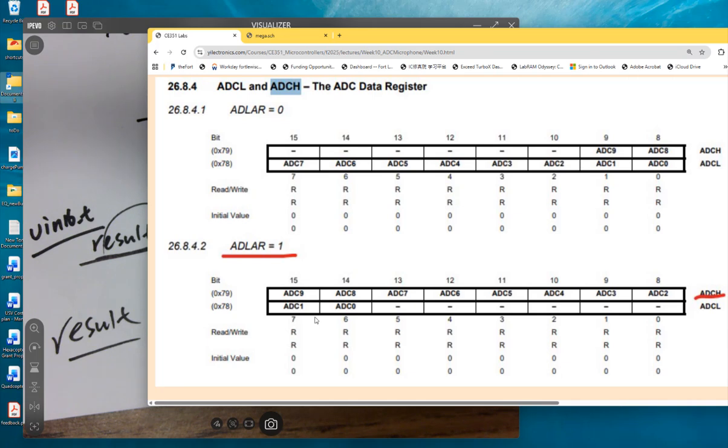Serial, UART. And UART is transmitting how many bits? 8. So if you have to transmit 16 bits or 10 bits, you have to send one first and another one, then do a lot of coding to receive and combine them afterwards. That increases a lot of complexity to our coding.